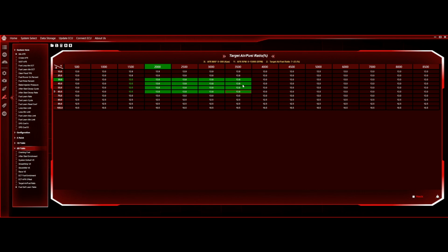For normal stock ported ones, Racing Beat and others suggest 8 to 10 degrees before top dead center for your base timing, and then with all of your mechanical and vacuum advances, that'll sit you at probably 40 degrees of advance in this cruising area, which is pretty fine. But yeah, that is just a brief overview of what I'm going to be doing for tuning my rotary engine with the Haltech system.